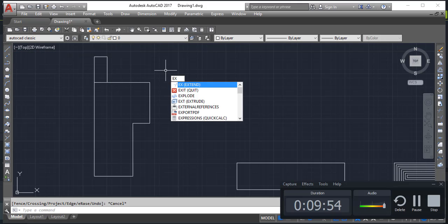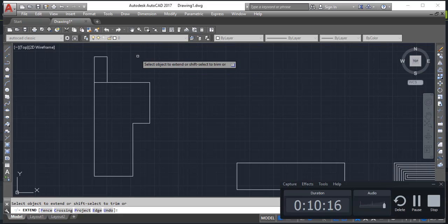So it's pretty simple, you just put down the command. Okay, so this is the easiest way in AutoCAD. Just give a command and apply it in your drawing, right? So extend. Right now for extend, it's also the same as we did in trim. So it's a double enter, right?